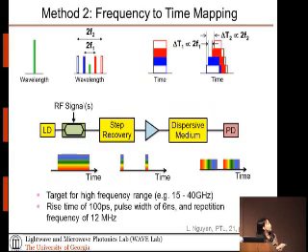So if you look at the upper illustration, this is the center wavelength of the laser. And if you have two frequencies going into the modulator, for example, F1 and F2, it will create two sidebands. One is the upper and lower sideband for F1, and the other sideband set is the upper and lower for F2.